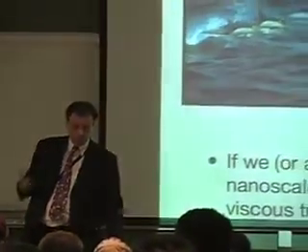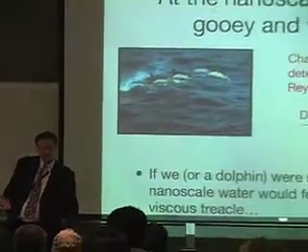And fluid mechanics tells us there's a number called the Reynolds number, which tells us the ratio of the importance of those two things. That's the formula. It's got a density, a velocity, a size, and it's divided by a viscosity. It's the ratio of the inertial part of the force to the viscous part. And the key thing is it's got a size in it. So at macroscopic scale, if you work out a Reynolds number for you going swimming, it's quite large. We're in the inertia-dominated regime.